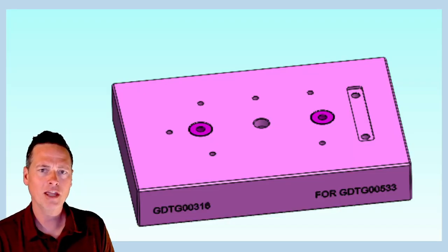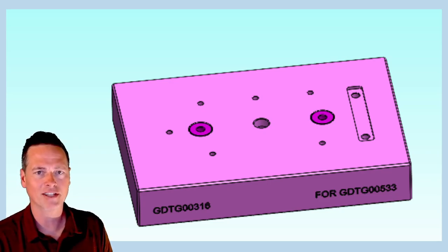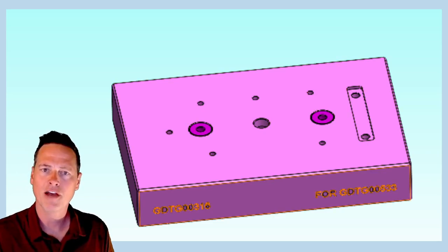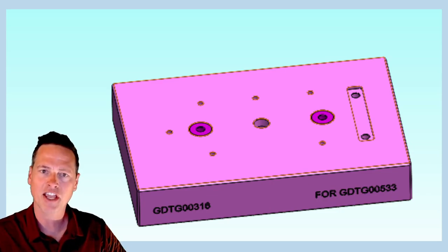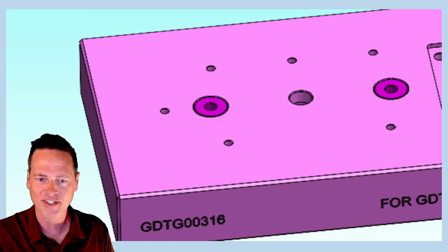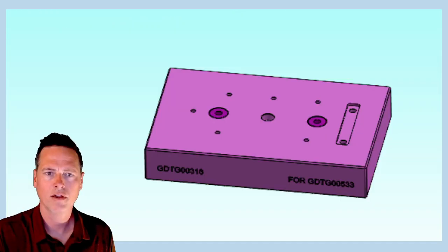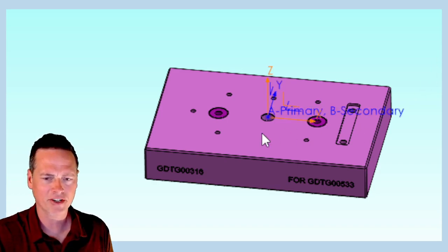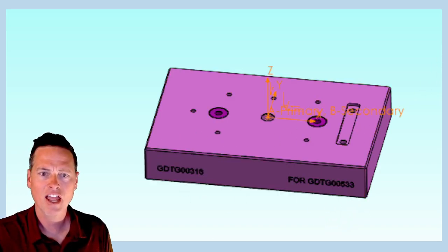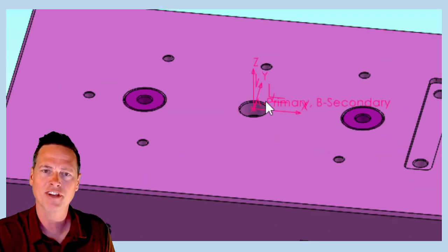We have two position requirements in two different datum reference frames. Datum reference frame A primary, B secondary at MMB could be simulated by a special fixture like this. We have our nice flat top surface datum A simulator. And then I put these fun inserts in here that would be our datum B at MMB simulators. My thought here is that the inspector could indicate in this fixture and then locate the 000 of that coordinate system right at the top of this center hole.